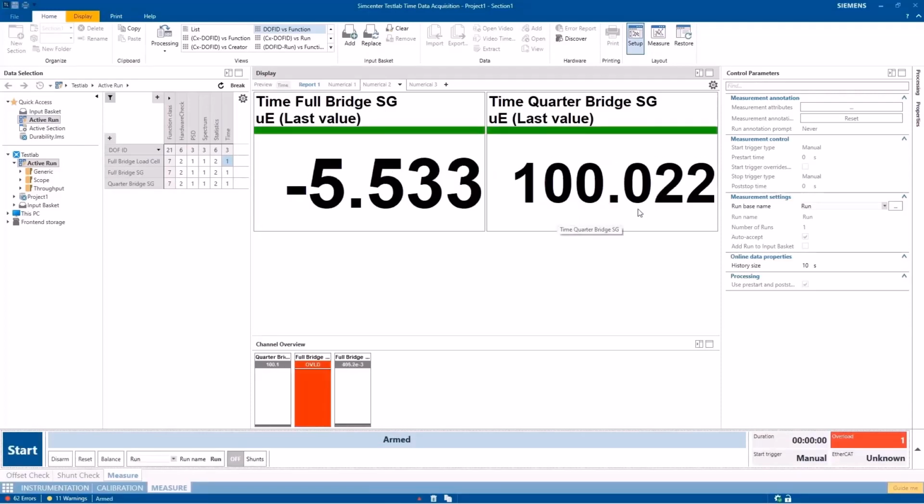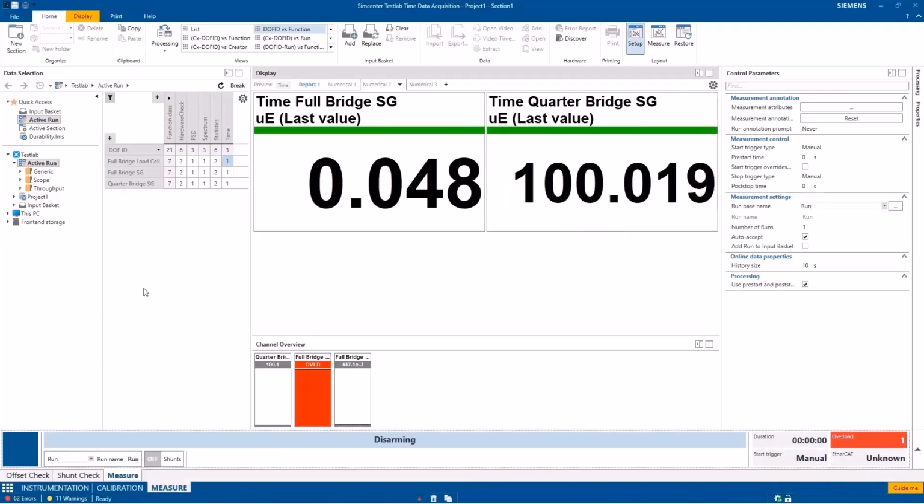Where this can be really useful, maybe not always with strain gauges, is if you have a DC accelerometer or a string pot, for example, where you might move that string pot into a position. Maybe the stationary position is minus 40 millimeters or 40 millimeters or what have you. And rather than calling that the 0 position, maybe you want that static position of the string pot accurately reflected in the software. So you could give an offset EU of 40 millimeters to that string pot, perform the balancing, and then the 0 will always be performed to that 40 millimeters.